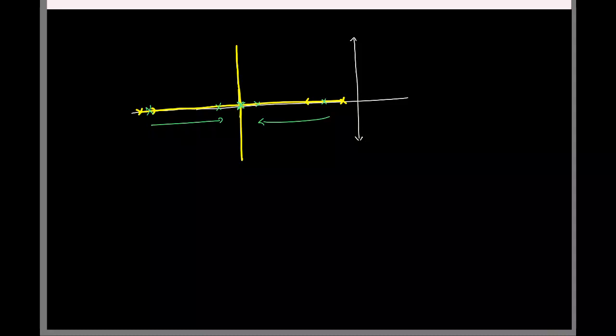Have you guys learnt about damping? No? Overdamped. And what is the damping factor? It's greater than 1. And I always prefer to write it in terms of quality factor, which is less than half. Okay. So this is where you have the poles on the real axis, but they are not equal.